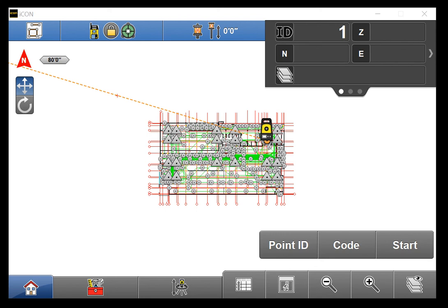It's important to understand that with this equipment, we can record virtually anything you can imagine geometrically. Some of the largest inhibiting factors are loss of line of sight and lack of experience with the software. This video is not meant to be a class on as-built surveys specifically, rather on how the software itself functions. But to understand how it works, you must understand what it's doing. The as-built program records location in 3D, which means not only horizontal points and lines, but vertical elevations as well.